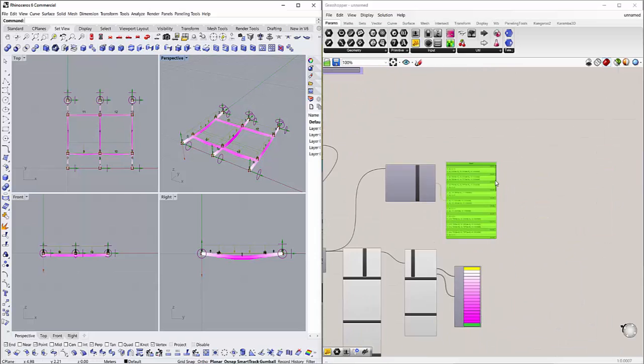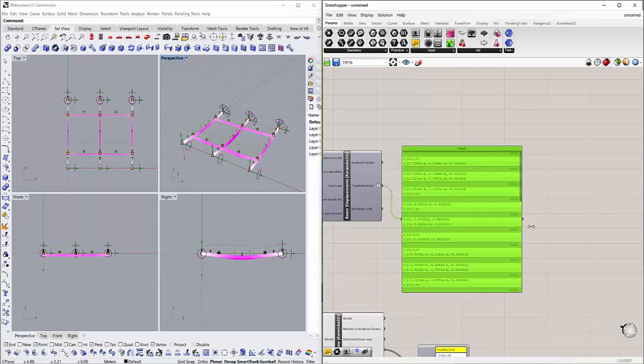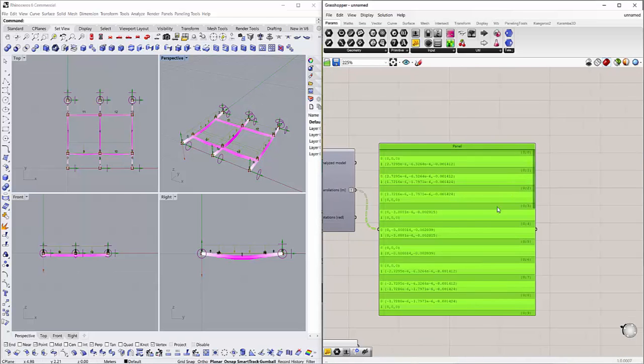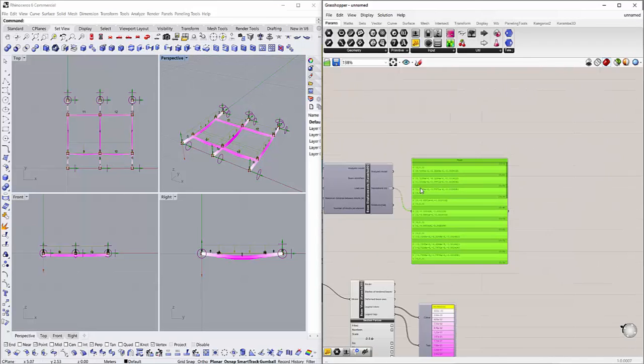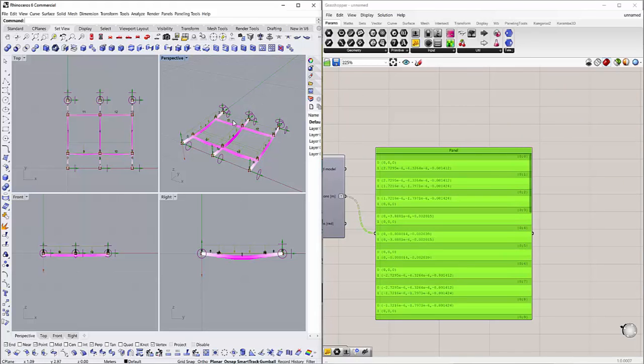So all these values of the beam displacement are as per the element tags. So if you can see here 1, 4 and 7. Okay, so now what you can do from here is you can check the displacement values for your mullions and transoms. So as we know the beam IDs here, so 1, 4 and 7.